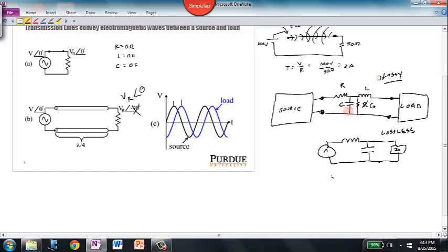The primary problem with it is that all the resistance of this wire here is lumped into a single element, and all the inductance of this wire here is lumped into a single element. Then the same for the capacitance and the conductance as well. In reality, these properties are distributed along the entire length. You know, the resistance doesn't exist just here. It's actually spread out over the entire length of the wire.